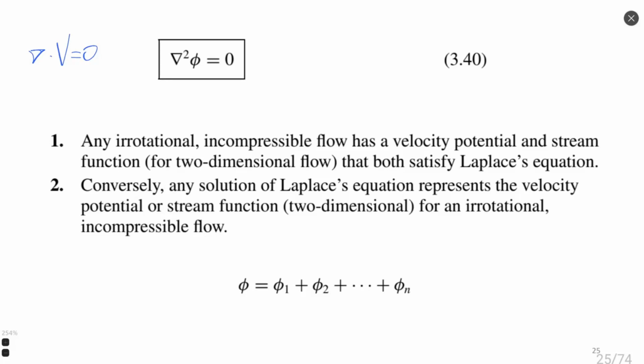First of all, the Laplace equation can be used for irrotational flow. Okay, but this is not the advantage. It's just a statement. Irrotational flow, so flow which is incompressible and inviscid. We cannot calculate flow with a boundary layer, for example, unfortunately.